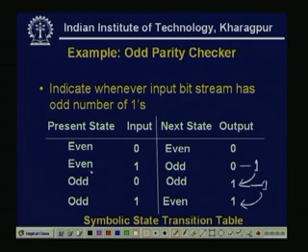So actually the even present state with input 1 will generate an output, and the odd present state with input 0 will generate a one output, and in the next clock cycle that will be shown as the output. That is why the output is shown here instead of in these places.